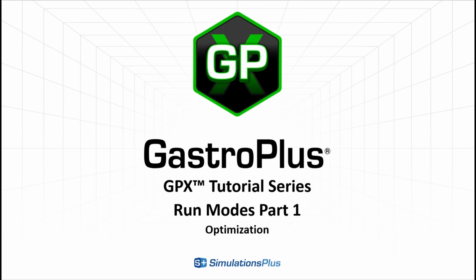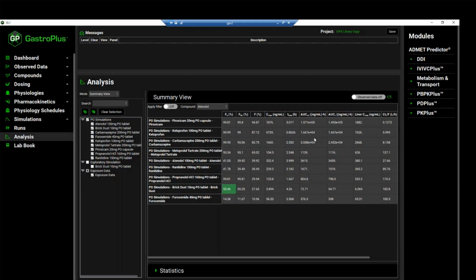We will continue to explore the run modes in GPX by running an optimization on the brick dust simulation. From the summary view, we can see that the fraction absorbed for the brick dust simulation was about 55%, and the Cmax was about 3.9 nanogram per ml. We're going to optimize the dose such that a Cmax of 10 nanogram per ml is obtained. For this, we will navigate to the observed data view,